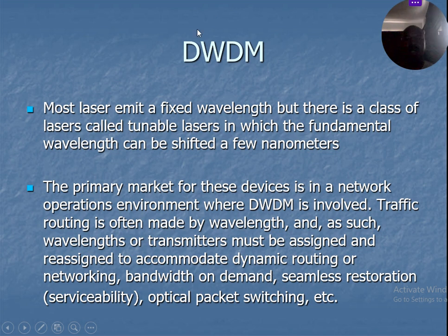What this means is that you have so many signal inputs, which will be coerced into one channel to pass through one channel, and then we get the multiplexed output, beginning with the modulator side, and everything goes through one channel. Then you get the output where the signals are brought out as demodulated values. This technology that synchronizes with optical fiber transmission is called dense wavelength division multiplexing.